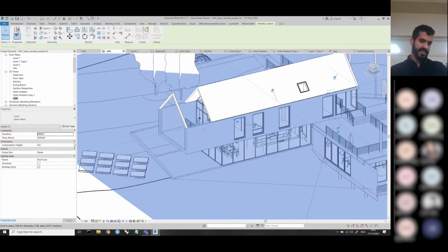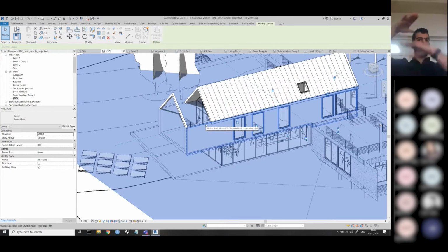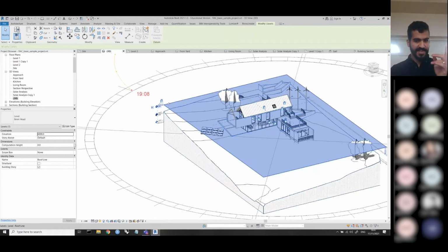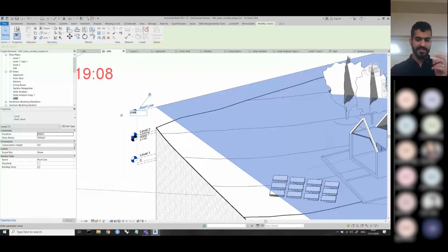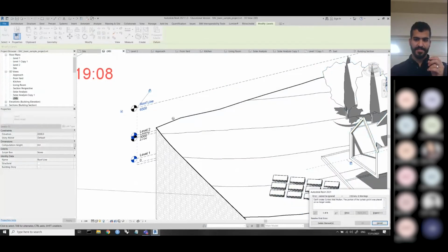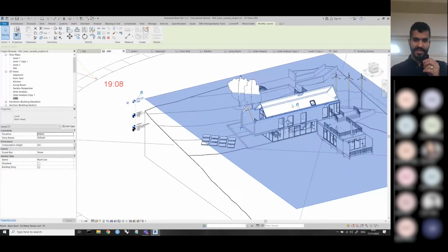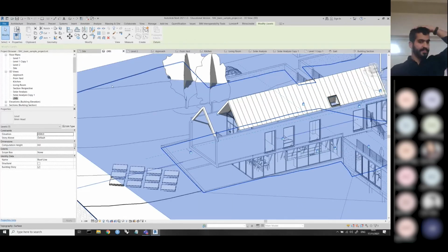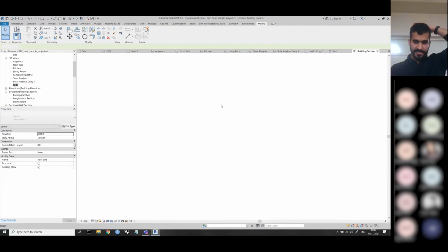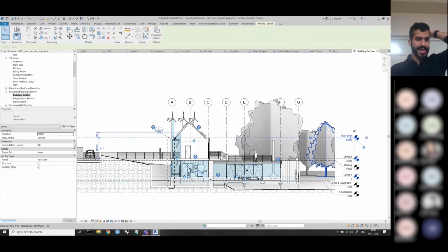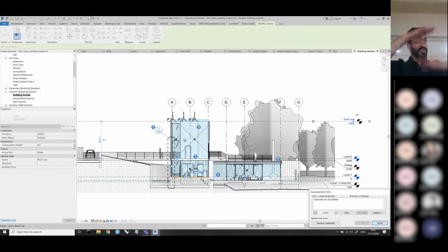Think of my wall over here. My wall is connected to the top level. It's connected to 2 levels. So if this model is modeled correctly, if I change this to 6500, enter, delete elements, whatever, I can see that my wall's gone up, or my roof's gone up. Again, if I go back in section, this is what I'm controlling. This is my plane. If I move it up, I'm moving my wall up because my wall is connected to that level. So everything is linked together, sometimes in inflexible ways, but that's how Revit works, right?